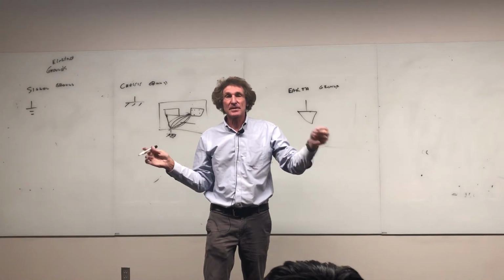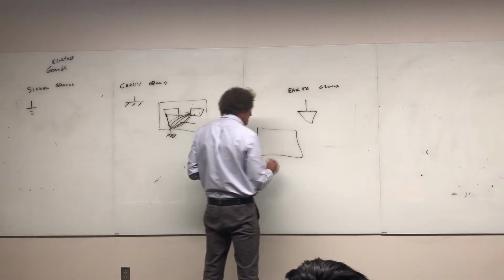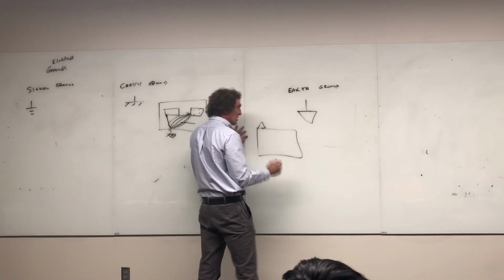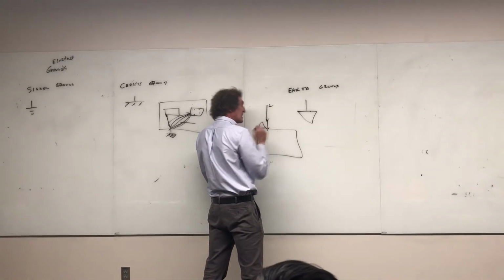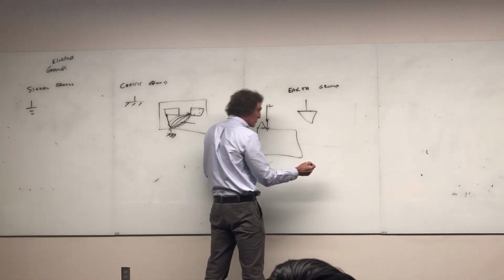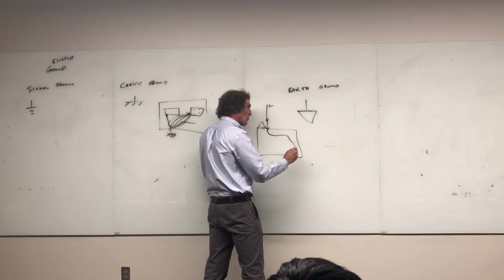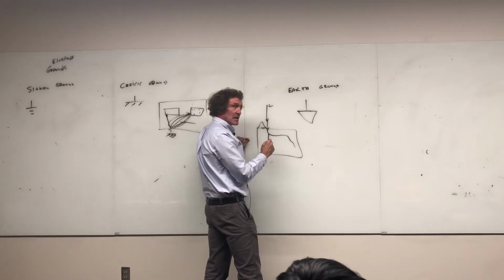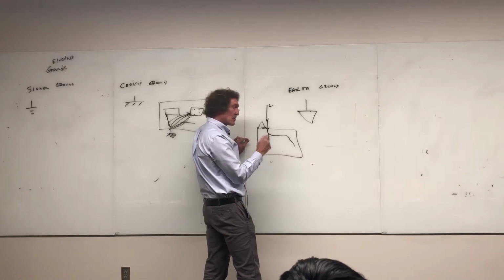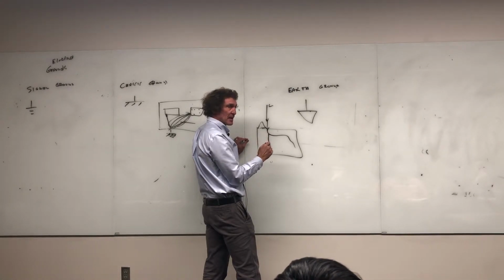We're teaching about this, and I said, if you don't use a proper ground on your house, and this is your house, well, when lightning hits your house, it wants to get to earth ground, and it goes through the path of least impedance, which may be some electrical wiring. It might be a cable, like for cable TV. Lightning has a fairly high current magnitude. It gets up to about 270 kiloamps, usually 20 to 50 kiloamps.